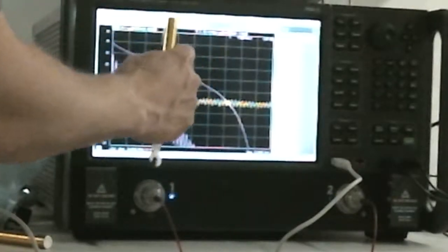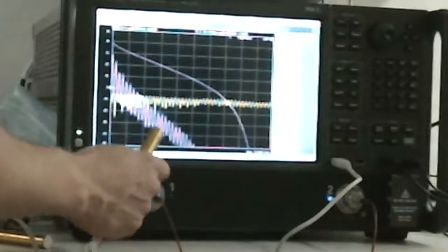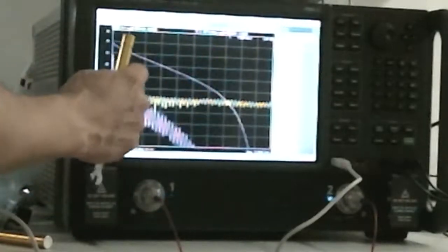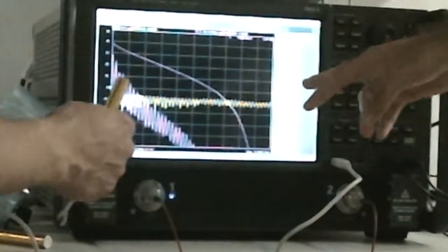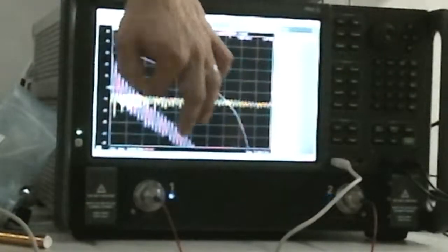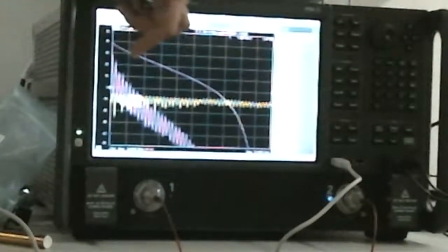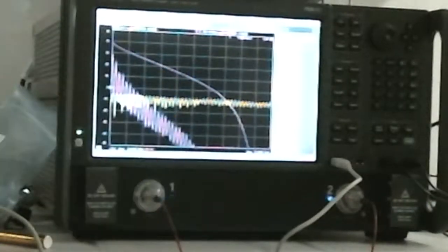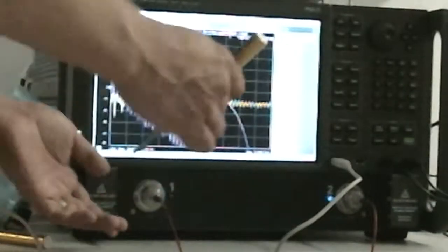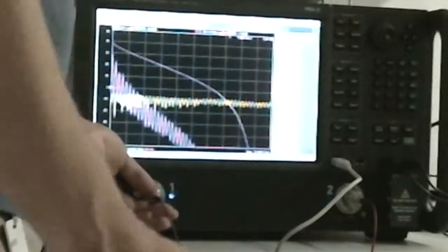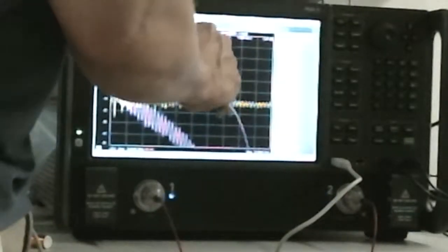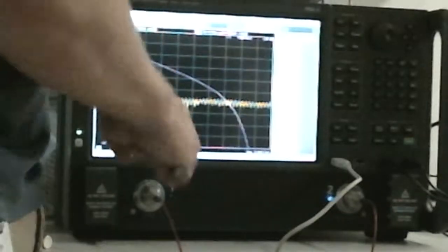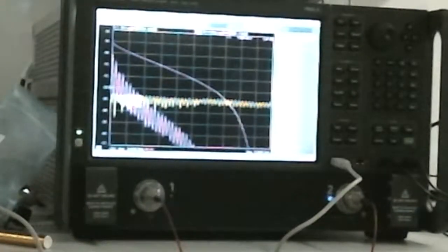If I go back to... what is this measurement? Oh, this is just the... No, that's the S11. The other one below, this is the insertion loss of this cable. So it's actually really poor at higher frequencies, because it's probably made for DC. It's probably made for shielded DC is what I would guess for this cable. So anything after even 6 gigahertz, this cable is not good. That's why it has like a gain or something. It doesn't have gain, it's just a different scale. So here this is the scale. Oh, okay. So you can have different scales here. That's just something to be aware of.